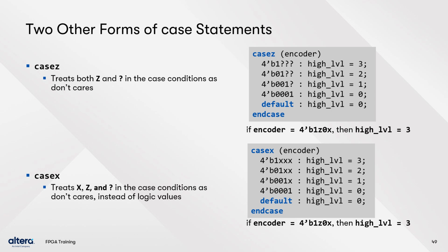However, there are two additional forms of case statements that won't follow this default behavior. The casez statement treats all z values either in the expression or the conditions as don't cares. The casex statement treats all x and z values as don't cares instead of logic values.